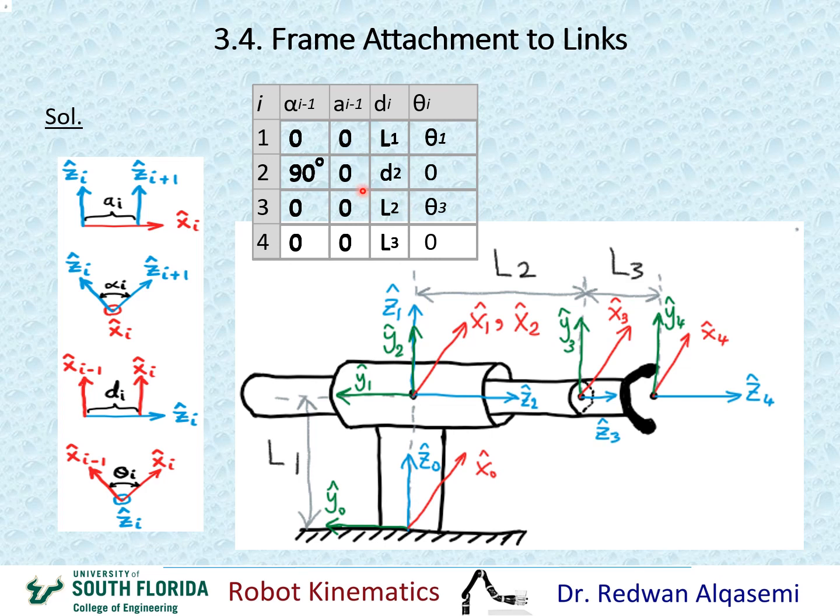For the third line, we have the first 3 elements constants and the fourth element variable, and that's because our third joint is a revolute joint. Okay, in the fourth line here, all of them are constants simply because we do not have a joint at the fourth frame. Okay, so since there's no joint, all these parameters will be constants. And now we're ready to go further with forward kinematics once we find the DH parameters, and we'll see how we can do that in later slides.